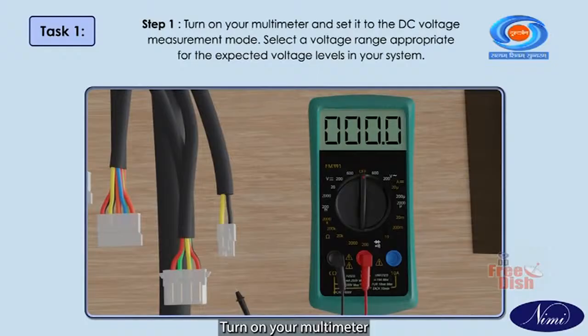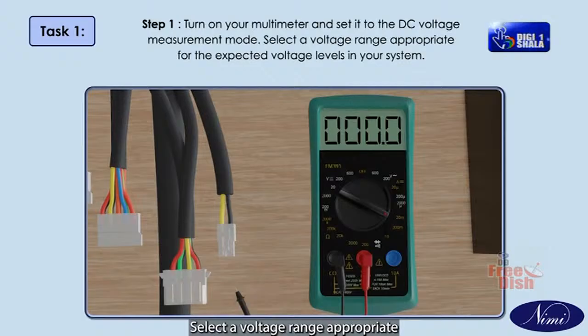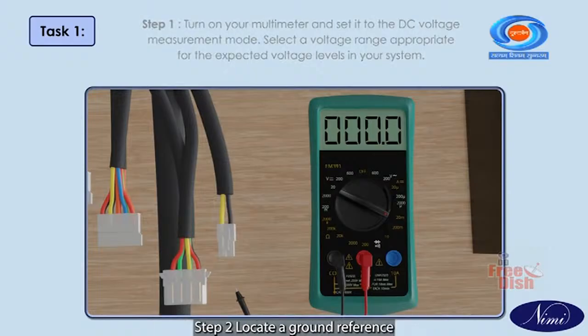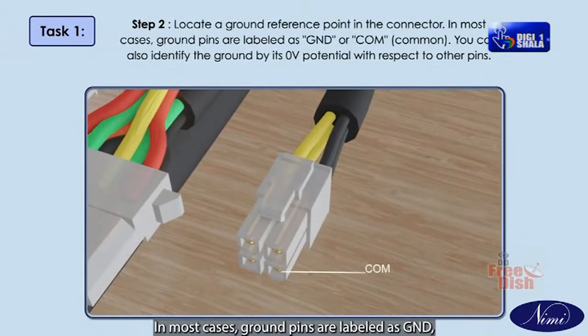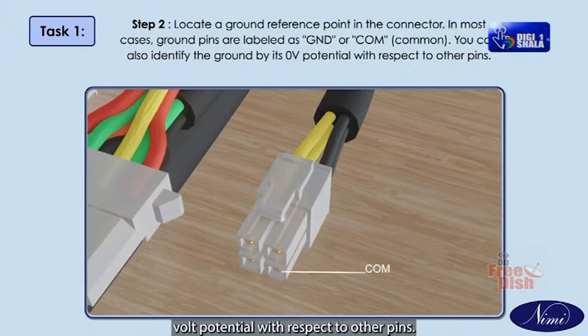Step 1. Turn on your multimeter and set it to the DC voltage measurement mode. Select a voltage range appropriate for the expected voltage levels in your system. Step 2. Locate a ground reference point in the connector. In most cases, ground pins are labeled as GND or COM, common. You can also identify the ground by its 0-volt potential with respect to other pins.